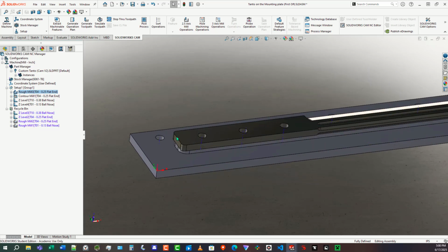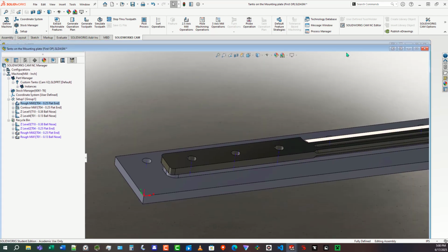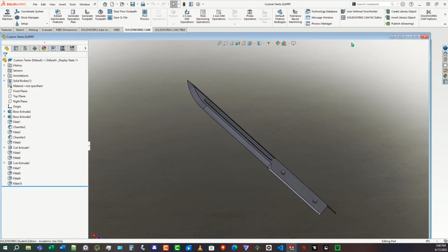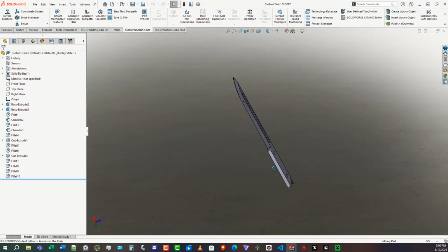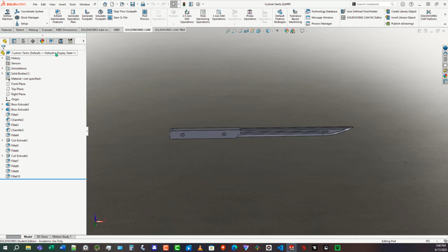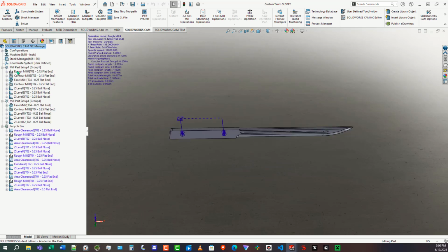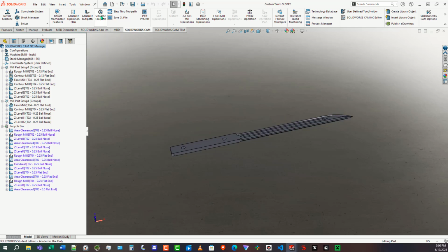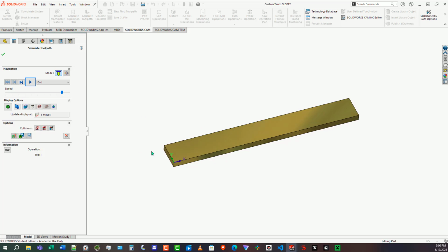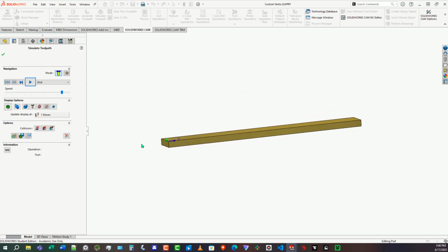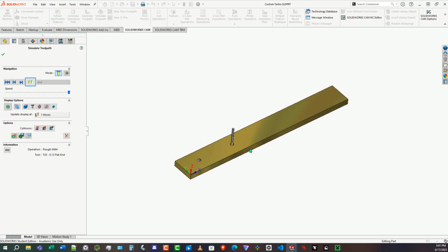But I still need to cut it to thickness. But if you see here, this is the knife by itself, which I also have some CAM for it, for facing and drilling. So if you look here, I still need to get it to the right thickness, because right now the stock we have is 3/8 thick. So if you look here, go to max speed, I need to drill some holes, I need to face it, and then I need to do the perimeter.